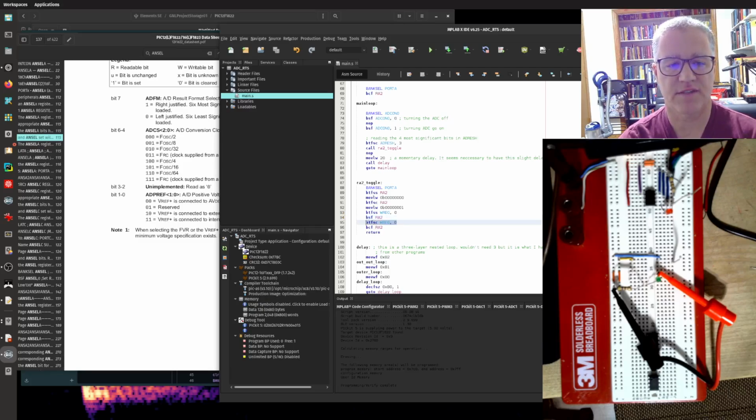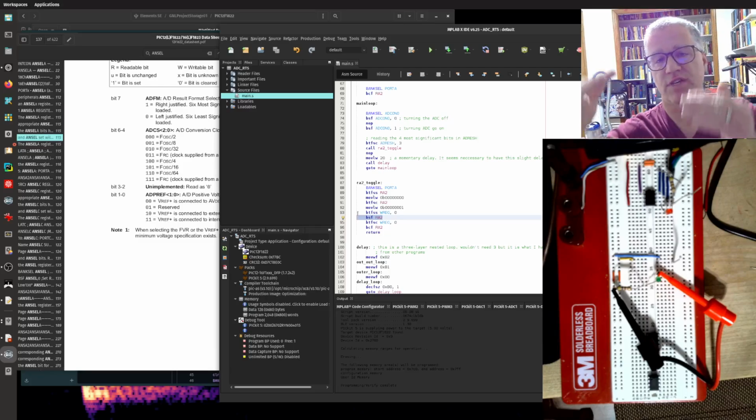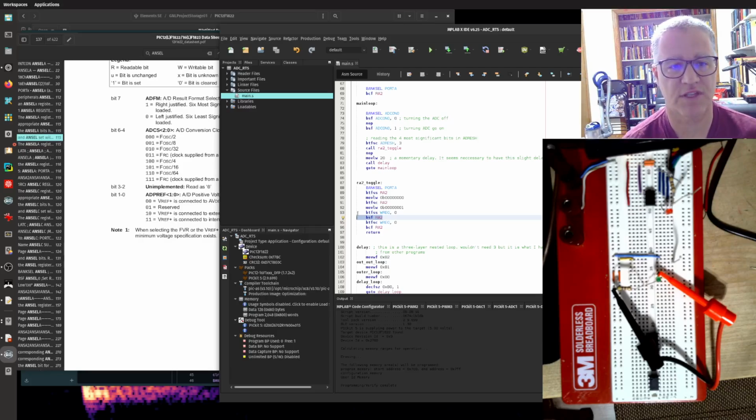And then if we hit this, our working register is 0. So it's clear, and we're going to skip this right to the return. So we're going to return with a set. So that's working toggle now. We come in with it on, we're going to leave with it off. We come in with it off, we're going to leave with it on.